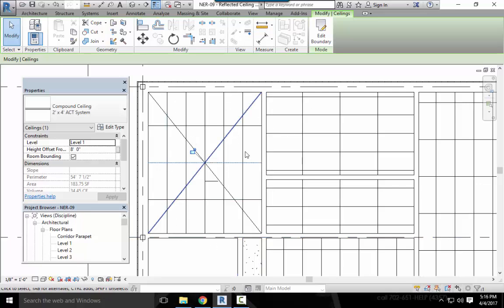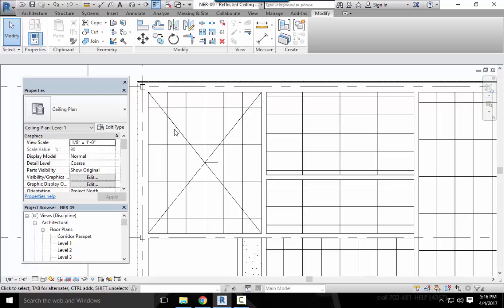If you had to put lights in here, how would you put lights in here? That's not a full tile. So you could only put a light there, a light there. And you want your lights evenly spaced. So if we undo that, now I can put a light here, I can put a light here, which is 4 foot apart, right? And I can go 4 foot here and put a light here. And I can put a light here. I can put 4 lights in this room and get a very even spread of light across them.